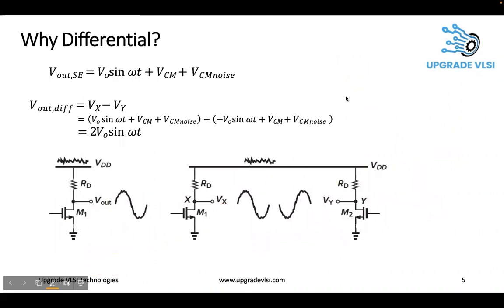So here one more example is shown. The supply will also have a lot of noise. This is because the same supply could power the clock generator or the oscillator. And the same supply, if it is connected to the IO ports, then IO ports usually take a few milliampere of current. Every time it takes a few milliampere of current, VDD will dip. So since it is connected to many other sub blocks, it will carry a lot of noise.